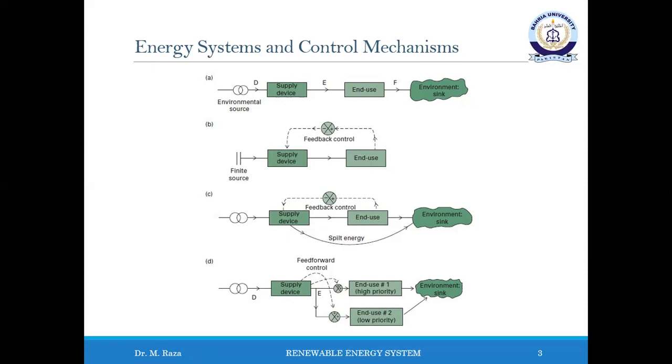For a renewable energy supply, negative feedback, as shown in figure C, results in potentially useful energy being wasted or spilt, such as shown over here. This is because renewable energy is a flow or current source in the environment that may only be diverted but not stopped. For example, a wind turbine operating at less than maximum capacity may produce more electricity than the load requires. Thus, controlling it negatively wastes the opportunity for more cost-free energy.